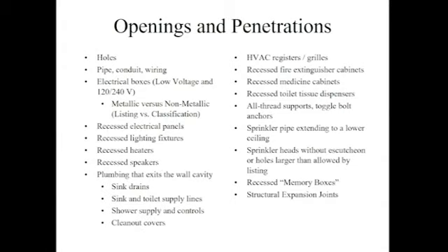Sprinkler pipes extending through the ceiling that have the pipe sticking down, those have to be fire stopped. If this is out of the IBC, sprinkler heads that have a solid metal escutcheon that entirely covers the hole are actually exempted under the building code from requiring additional fire stopping.